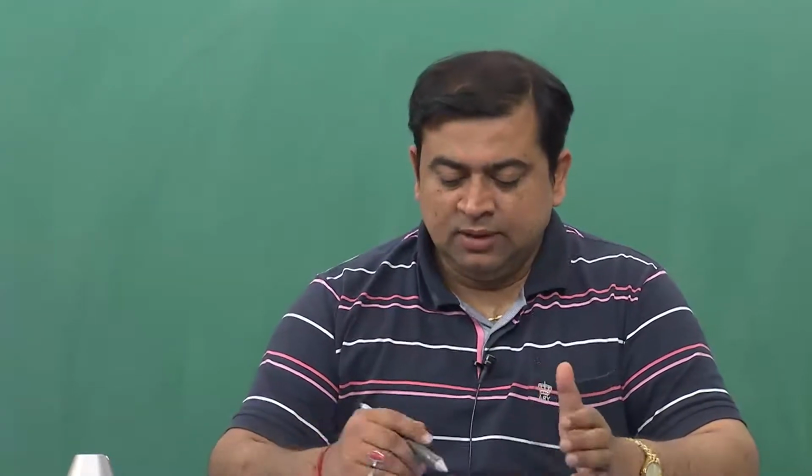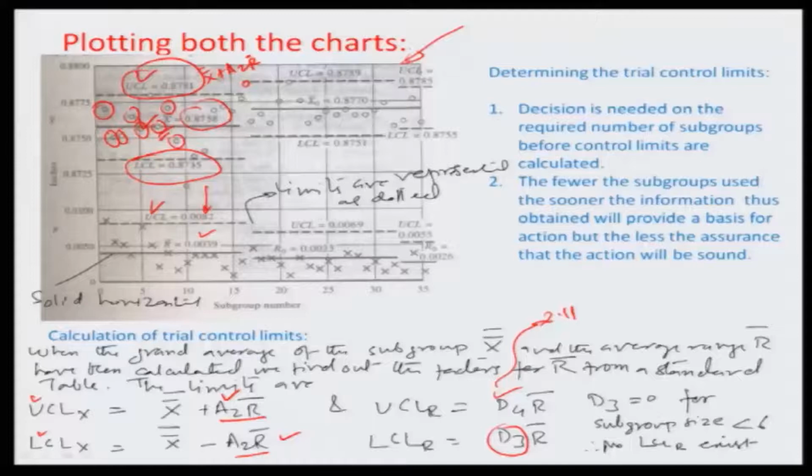So, there are some variations, as you can see from case 1 to case 2 because of that, and similarly from the range chart also, they are quite variable in terms of their mean or the UCLs or the LCLs and how far they are away from the mean. Obviously a tighter or better control can be reflected in probably the second case here, because it is accommodating for that factor of post cooling recording of the milling slot width in question.